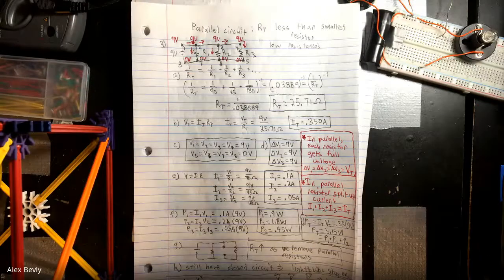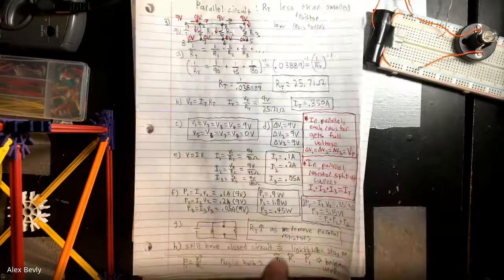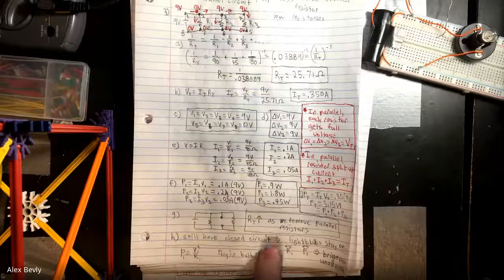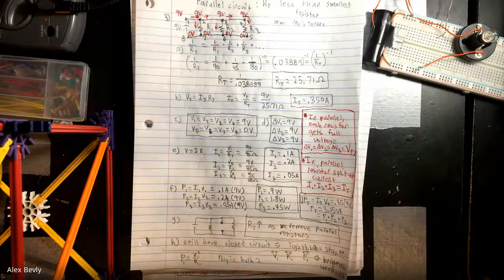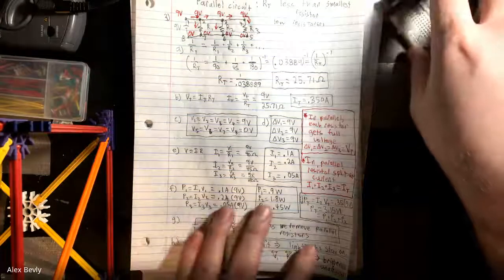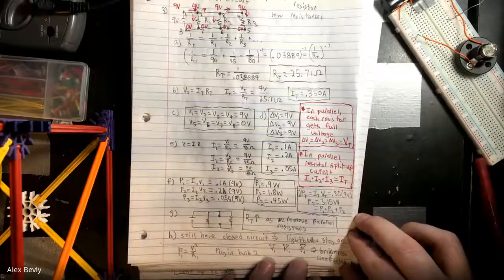When you directly start up something, your vacuum cleaner draws like 5 times more current than it normally does. And that's a little bit different because you're suddenly drawing more than the circuit can provide, and then things dim, and then it goes back to normal. So that's a much more complicated interaction actually going on there that deals with alternating current circuits, which are more difficult than what we're doing on here. It deals with something called inductance, which, if you want to talk about that, go into Physics C.